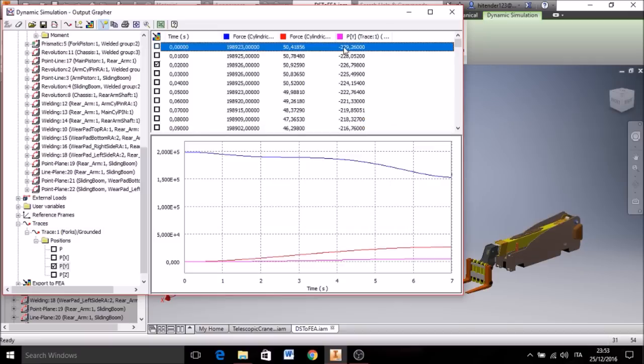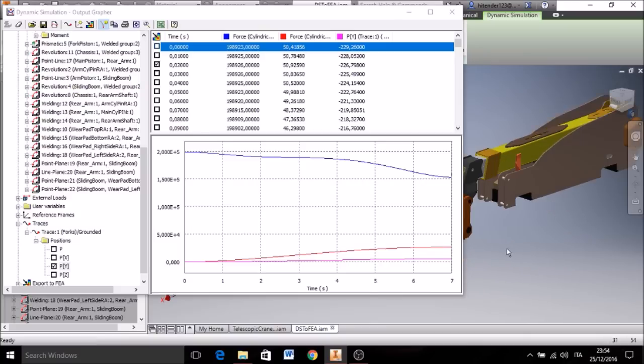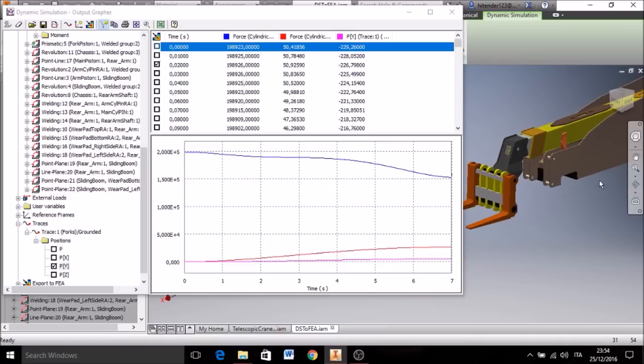and we can see that it has started from here, from -2 to 9. It is in minus because the point as a reference is a little bit above the position of the point I had selected. It was somewhere here, which is a little higher. So it started from negative and then it goes to the maximum value. So adding these together, we get approximately 5.6 meters of height. So this machine is capable of lifting this load to a maximum height of 5.6 meters.